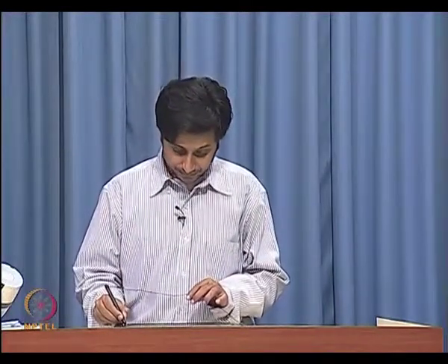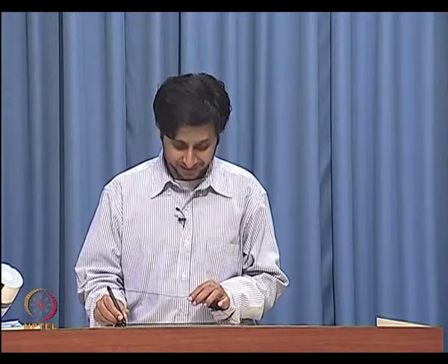The fact of the matter is that this issue of analyzing phase noise has been dealt with in several research papers, right. There are several techniques talking about how to compute the phase noise in an oscillator. Unfortunately, they all have some deficiency or the other. Now, you are going to ask, where is the deficiency in this technique? The deficiency in this technique is in the fact that we did a small signal analysis. The very fact that we did a small signal analysis is wrong because of two reasons.